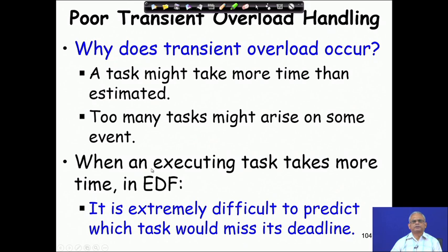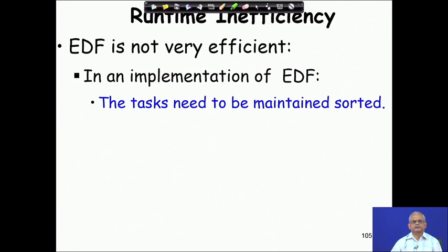Maybe it could not write properly to the disk and was taking more time, but if we do not log events, nothing very severe happens. We would not want that situation, that due to an event logger or a result logger, the critical task misses its deadline. But in this scheduler, that can happen: just because the logger task is taking more time, the critical task missed its deadline.